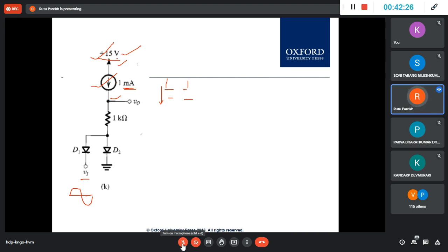So this is external to the circuit and has nothing to do with any circuit. Whatever voltage source is there, above or below, will have no impact on the value of this current source. So this is the king, the boss. You have to forget it, whether it is 1500 or 50, whatever. You forget this and take this as your circuit now. You start from here and take this as 1 milliamp, which is going to flow through here. So your circuit is now reduced and this is no more there.